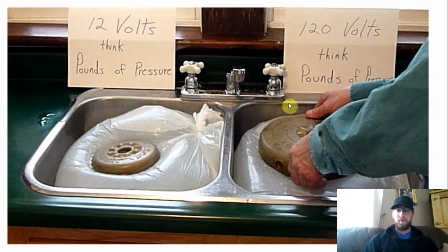And then let's say while that water's flowing out, we were to grab a measuring cup, okay, and we put it under that stream of water coming out for 1 second, and the amount of water we were to grab in that 1 second, that would be the amount of amps, right? So depending on the amps or the volts of a circuit, there will be varying needs for the gauge of wire that is used. The more amps or the more volts, the bigger the wire needs to be in order to handle it without overheating.